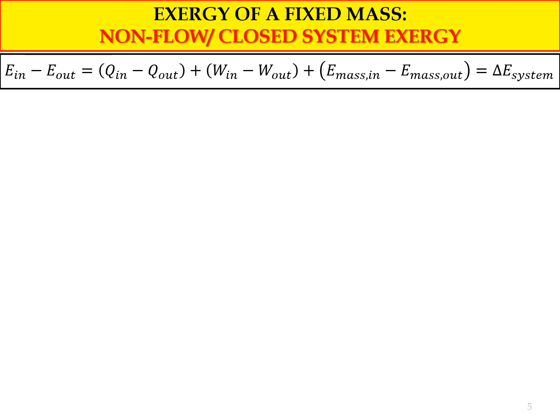So this is from the energy balance equation. So we expand the system, and we consider three energy coming from three sources, which is the heat, work done, and also coming from mass flow rate in and out.